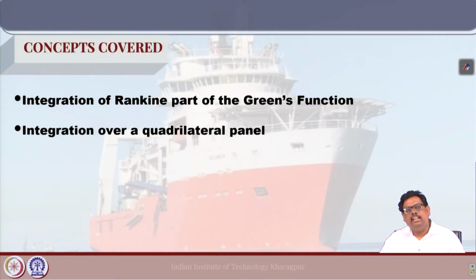Now, in this lecture we are going to again discuss how to integrate the Rankine part of the Green's function. In the last class we discussed how we can integrate analytically when the source point and the field point are very close to each other. Today we need to discuss how to integrate over the quadrilateral panel.